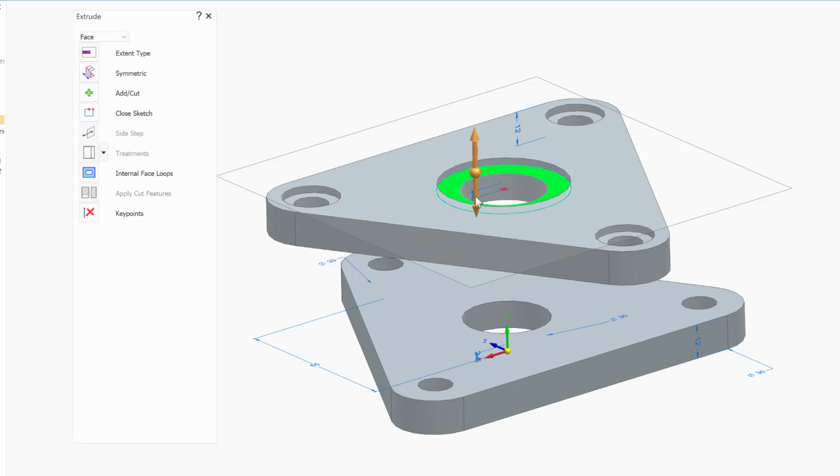So I need to go down. How much? We know that the distance from the top to the bottom is 60, so this is 12. We go 5, so we need 7. So I need 7 plus 36, so 43. Any dimension above 43 should work, like 45, 46. That's good, because I still have 12 here. Or in another way, another 7.